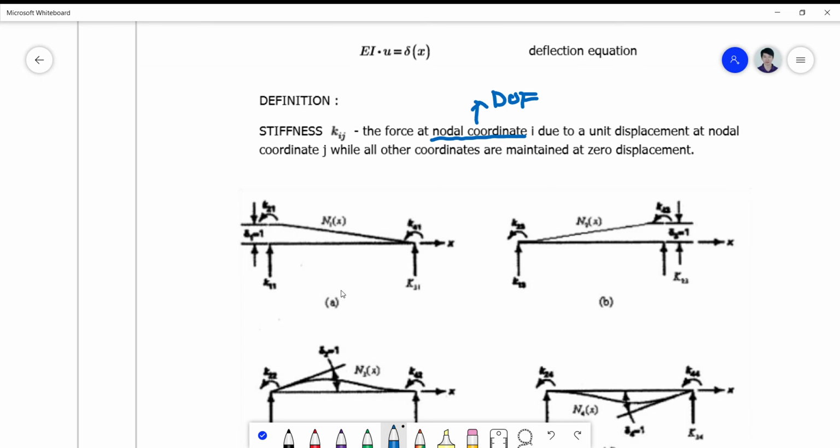So if you have here a unit displacement of 1 on translational, the others are fixed, no? So the unit displacement here in terms of moment or rotation is 0, and the translation is 0, and with this one also 0. So what is only assumed to have a value is the coordinate 1, which is simply given by the nodal coordinate in terms of translation.